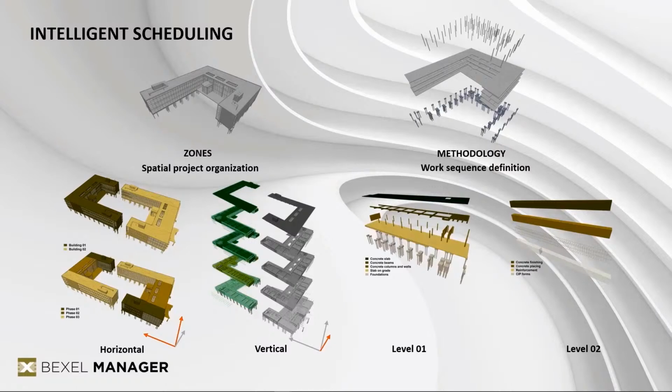So if you have multiple buildings, you're going to divide your schedule by buildings. If you have multiple stories in each of these buildings, you're going to define the subtasks for the stories. If you have multiple zones on one story, you're going to define these zones or phases as well. So this is one part of the schedule organization.